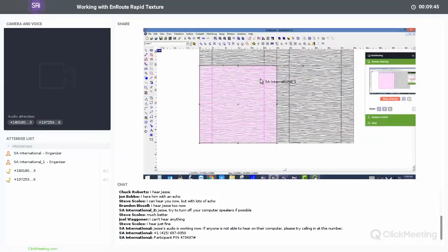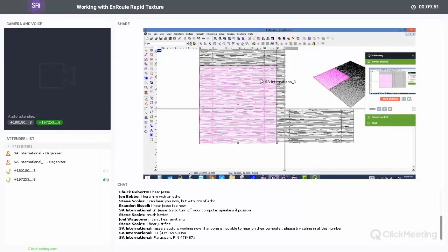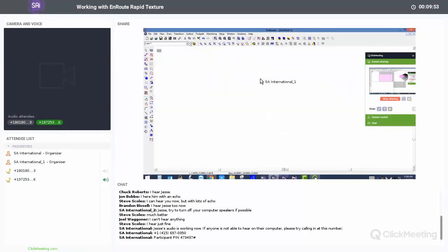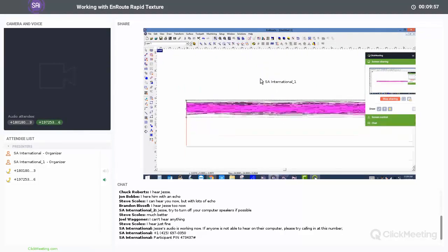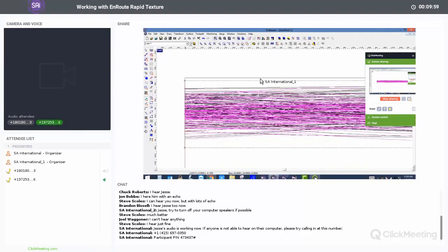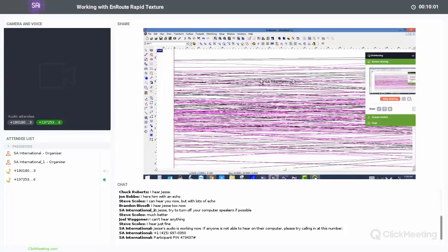Okay, on the top, you will see that the lines are inconsistent, but the more impressive feature is if we go into the front view, we can see that there are individual lines here, and once again, because we clicked on noise, we are individually distorting them, and we get a lot of random texture throughout this, which we're going to go ahead and apply a toolpath to.